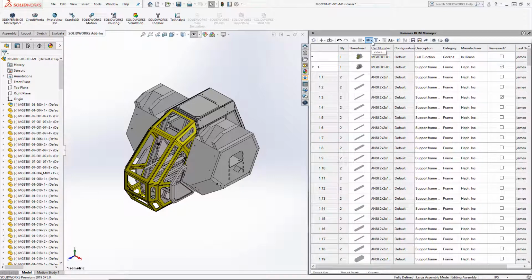Start by finding the view icon in Bommer, which is the icon that looks like an eye in the toolbar. Clicking on this will open the Views drop-down menu, which lets you select an existing view or edit your views. If you want to change your view, you can select one of your saved views at the bottom of this menu, and the table will reconfigure to show the columns selected in the view. You can also press Ctrl E from the table to pull up a view switcher to achieve the same result.